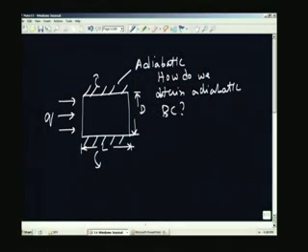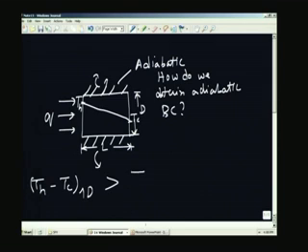So, what will happen is that if you have Q here, some amount of heat is lost here and the temperature difference here, let us say Th and Tc, will be smaller than if no heat loss were taken. That is right. This is Th minus Tc one dimensional, which is greater than Th minus Tc two dimensional, where you have heat loss on this side.